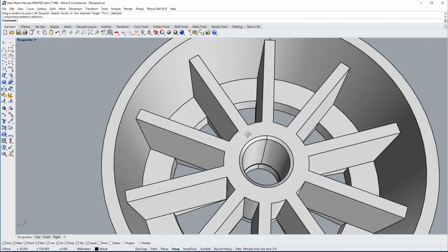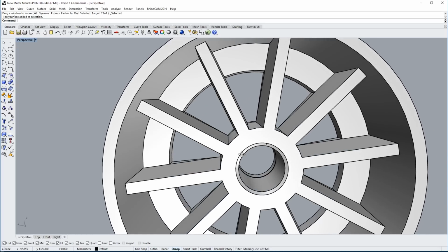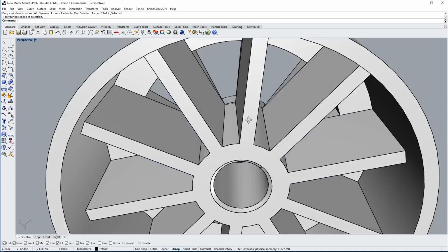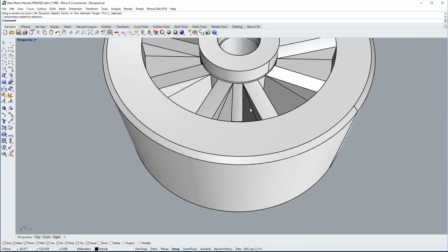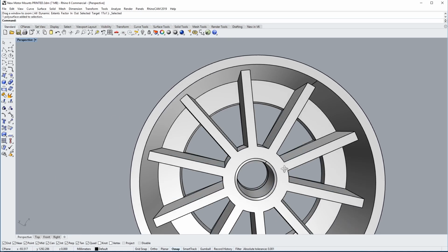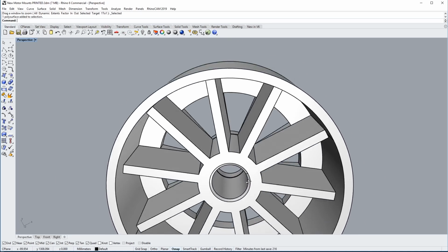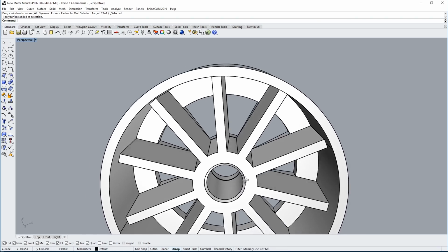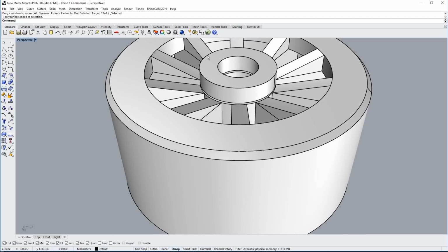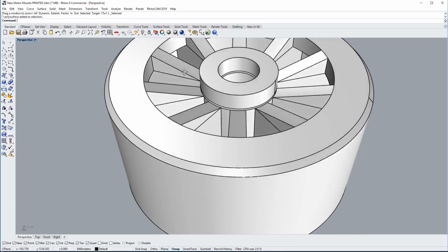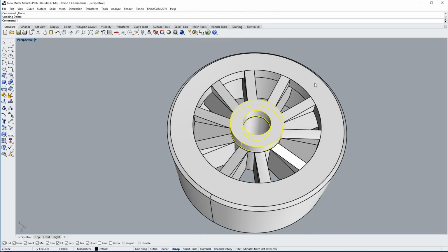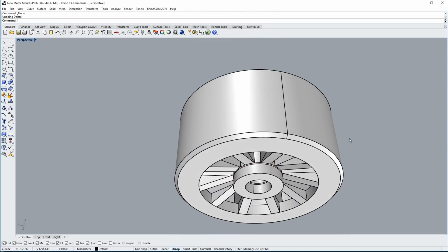It's pretty much the same technique that they used on the stock fan. And that means that the blades here are 2 millimeters at this side, and then on the other side they're 3 millimeters. So that's not very steep angle to those blades, but at 12,000 RPMs, it creates plenty of downdraft across that motor to cool it down. The one thing I kind of changed up is you can see these sort of angled pie-shaped pieces there, and that's just to help with the printability of it. You'll just throw that piece away. That's just sort of like built-in support material.